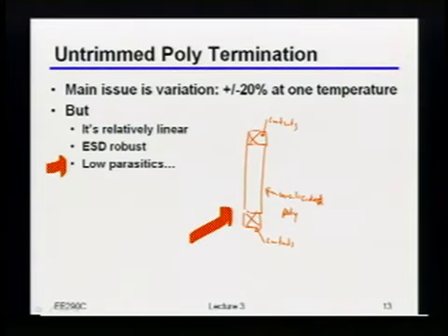What we're talking about is 50 ohms. So remember, even if it's 50 ohms, I can't do a 0.1 micron wide metal wire and actually get 20 milliamps of current through that thing, or even 10, or even 5, or even 2. I actually have to make it pretty wide, which of course means then it has to be pretty long. So you're right, there may be cases where you can get away with it, but generally speaking, you're still better off with something like an unsilicided poly, simply because for parasitics, you want it to be physically as small as you can make it. Does that make sense?